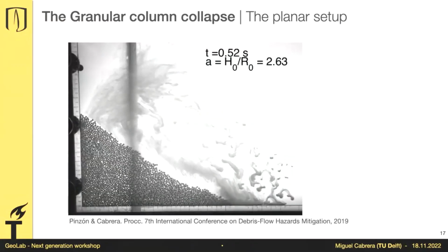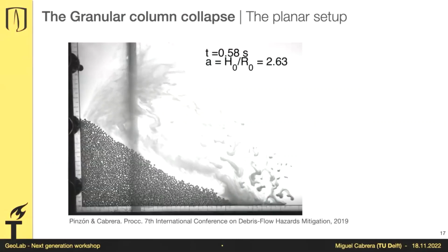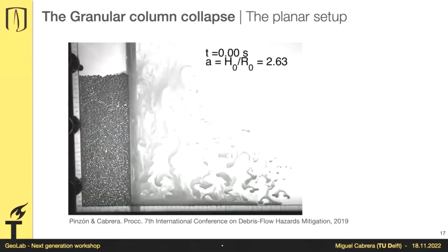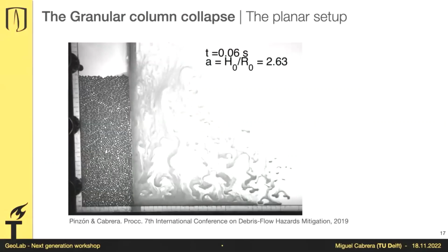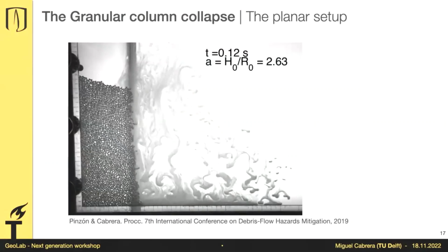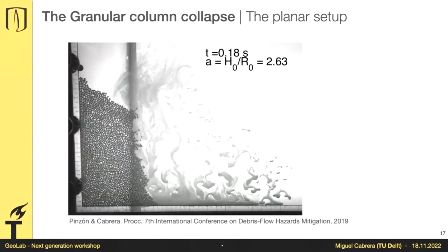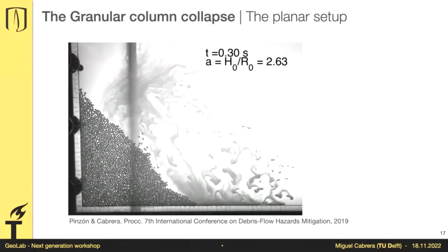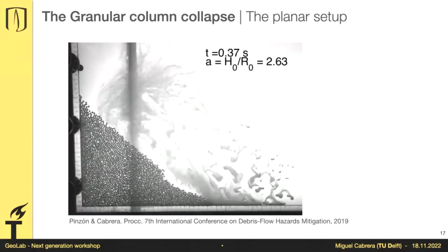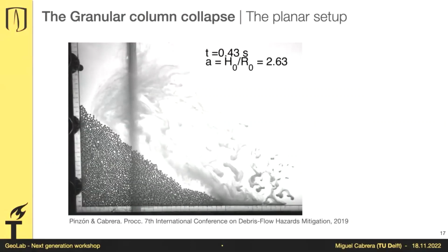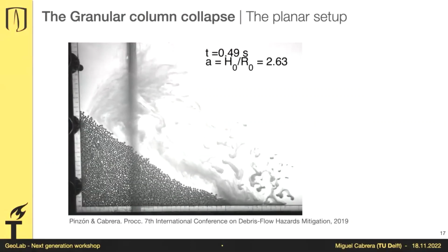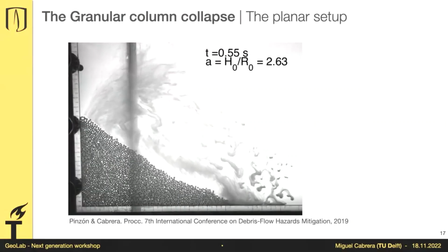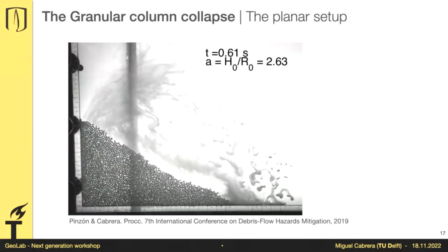So all these stains you see here are a tracer for the fluid. What I want to catch your attention to is that once the landslide happens, it's dragging water from the top that moves towards the left. That water is being continuously dragged. And eventually, when the landslide is reaching its deposit, it starts to expel water. Please note, to the front of the landslide, that white region that is appearing. That is water that is pushed away from the landslide.